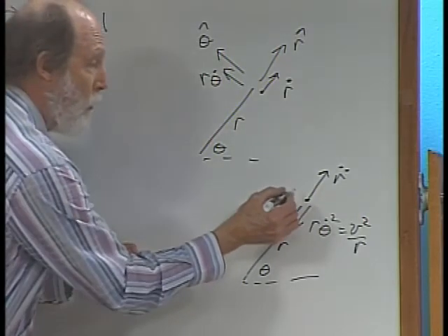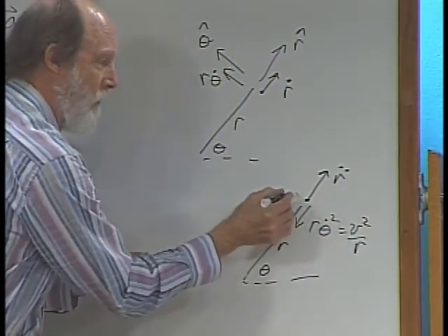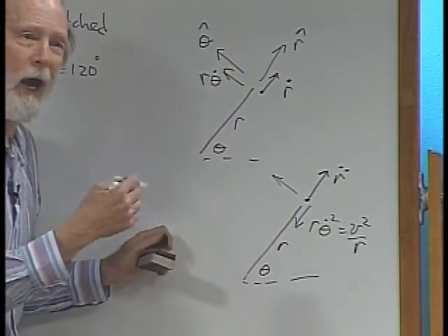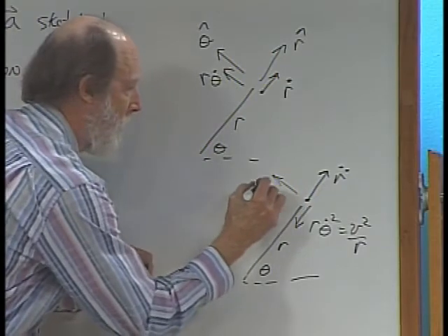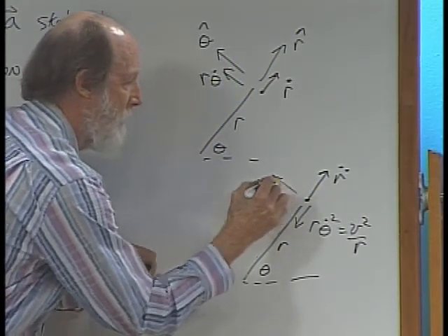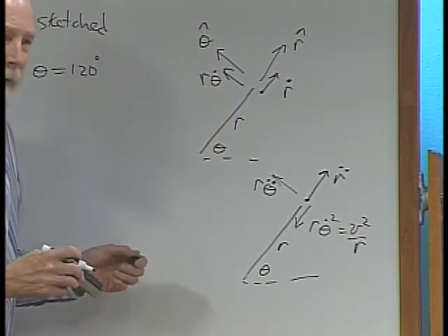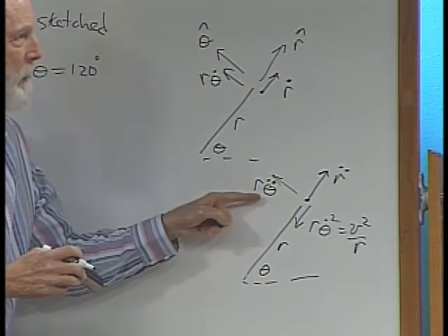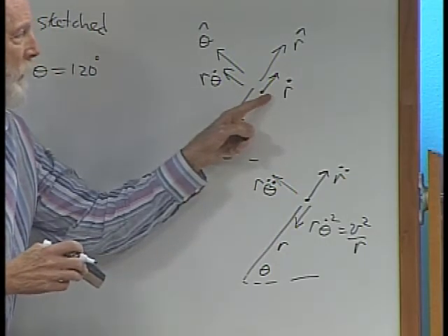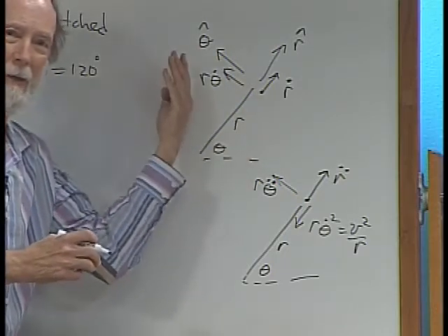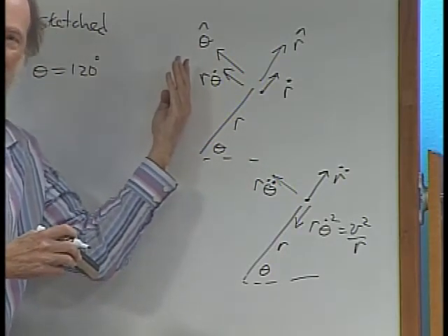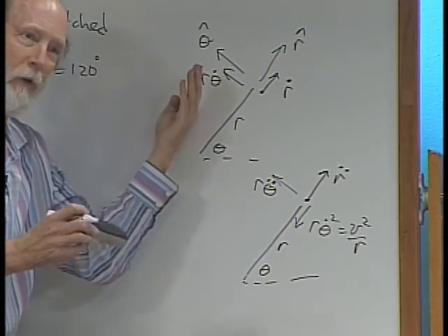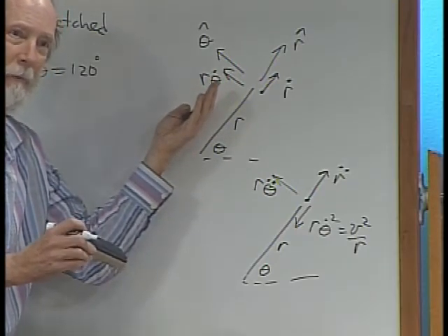Okay. Now, the thing could be speeding up in its rotation about this pole. So there could be an r alpha type of term, which is going to be an r theta double dot type of term. And then you also have to think that there is a term when you're moving radially on a rotating body. I mentioned this last week, and you'll hear me say it again several times. If you're moving radially on a rotating body, there's going to be this other term called the Coriolis term.